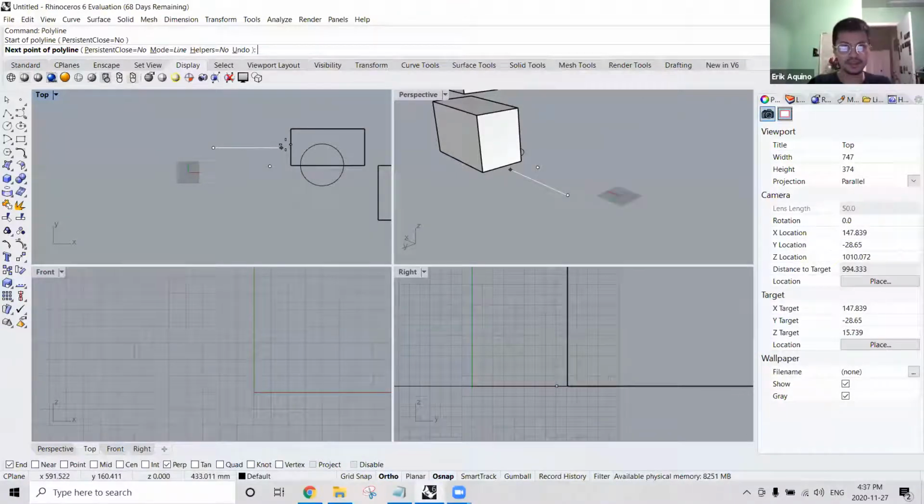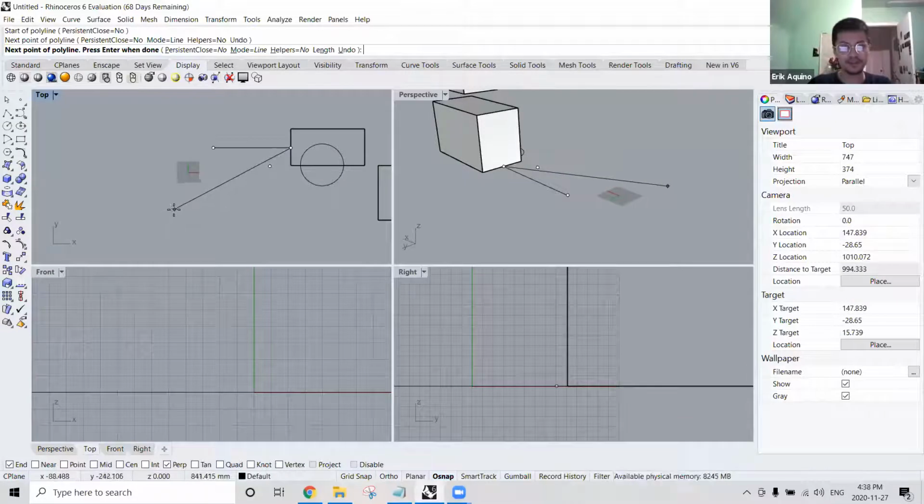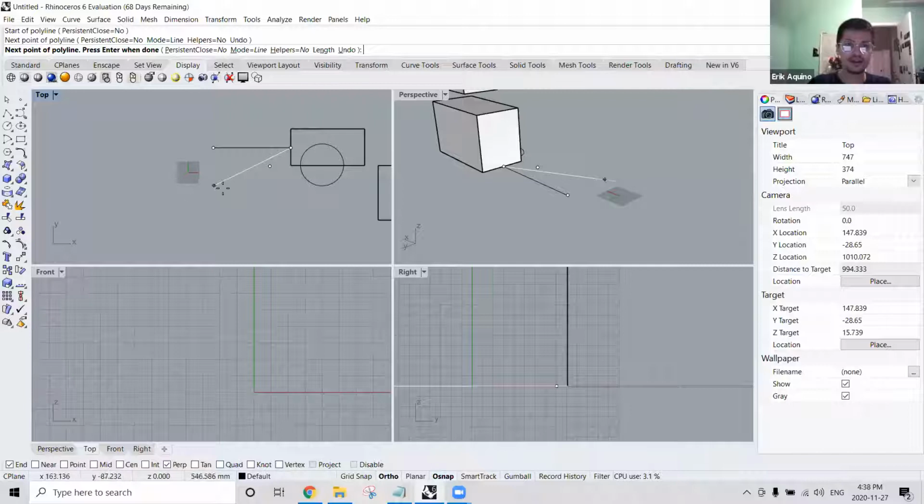That should lock it in the same direction that you've placed it in, essentially. So when I click my prism as my datum, it's not going to lock onto the top. It should stay in the same direction. That works if you have an angle as well. So I have it at an angle and I'm hitting tab, that should lock into the same direction and the same plane.